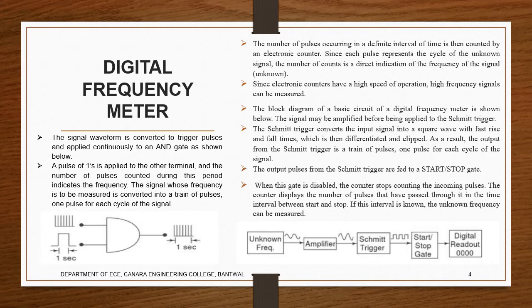So what we are doing here is, the frequency has to be captured continuously for 1 second, for example. We give a certain number of pulses for that to make it work. After that, we don't provide pulses. So the pulses provided during that one cycle, for example here I am taking it as 1 second, that much time the pulses will be recorded at the output.